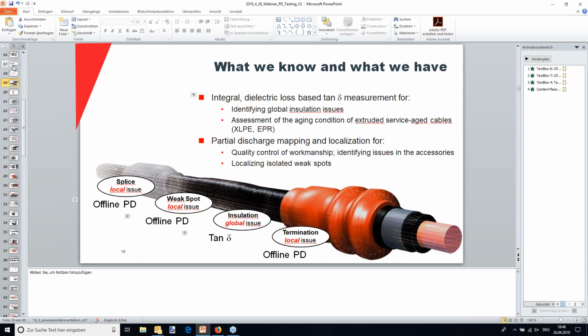Air and vacuum, air has approximately 1. So if you have a material like XLPE and its permittivity is 2.3, that means the field lines are 2.3 times more intense than in air. So if you have a rubber mat or anything made out of a material that has a significant permittivity, you create a hotspot for the field lines there because the field lines are compressed into the dielectric material and you create more corona.